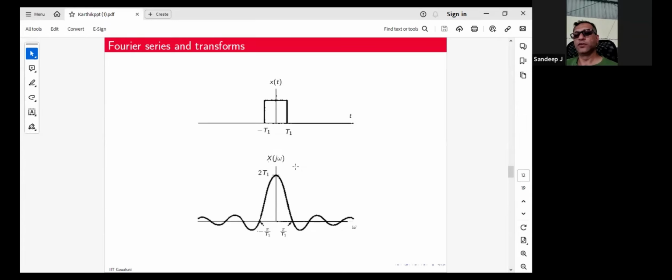If I take a conventional preamplifier where my load does not consume a lot of current, and much of the stuff works in pure class A and relatively symmetric, I get a relatively proportionate harmonic structure, like a dominant second harmonic, and then a third harmonic in a relatively proportionate way.